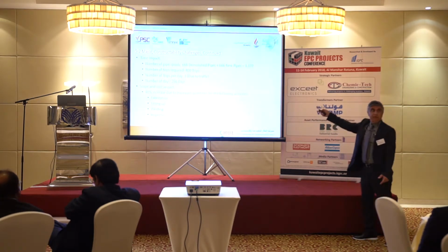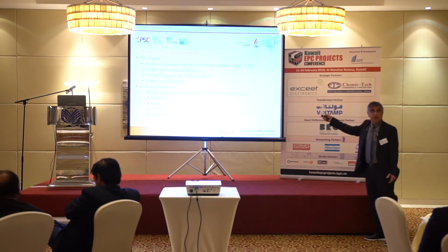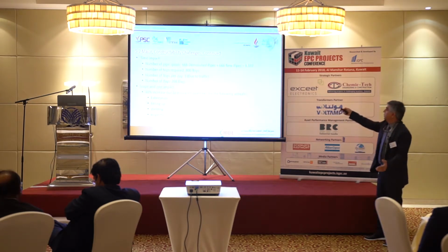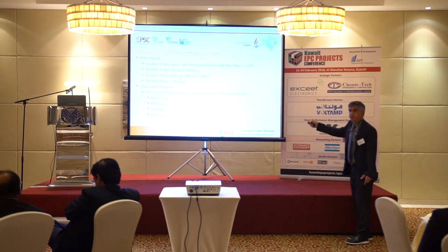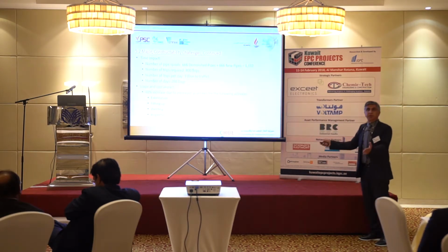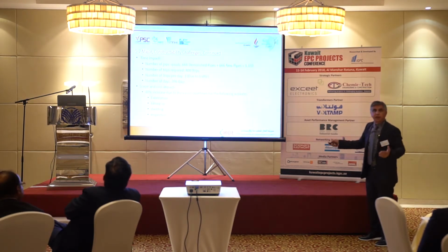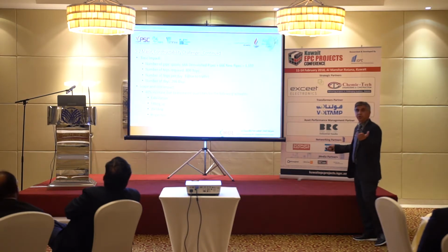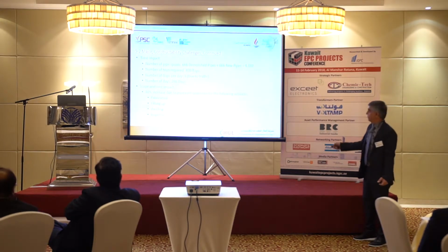This is the time impact. The number of pipes is about 1,332. The number of trips, with the constraint that we have for this road, is about 800 trips. So you can do only 3 trips a day, that's the best you can do, and this will lead you to almost 1 year. Now the scope: of course, you're cutting 6 meters, you cannot cut more. So there will be an increase in cost, about 40% we evaluated, in the fabrication, fitting, welding and inspection.